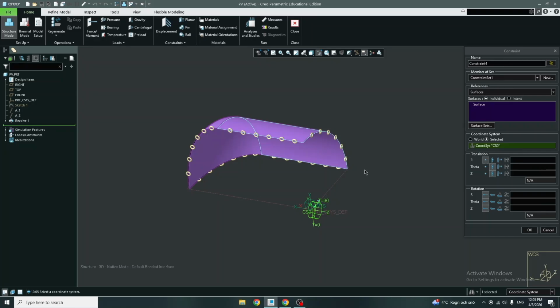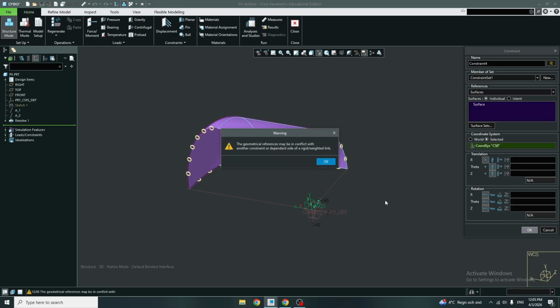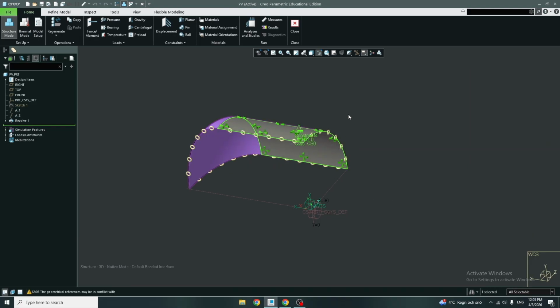So you're going to let the cylindrical surface deform in the radial direction. In the hoop direction and in the longitudinal direction, you're going to lock them or fix them. It's going to be fixed, but in the radial direction, it can be free.